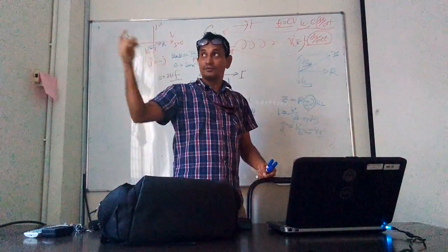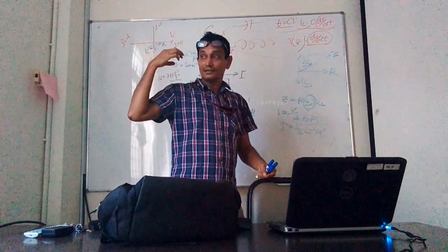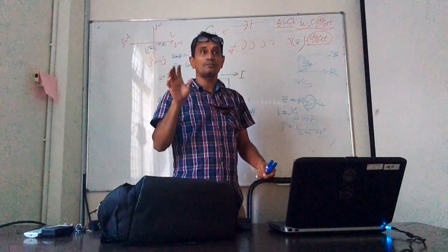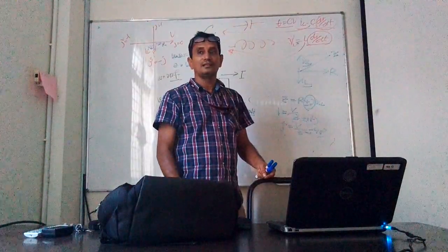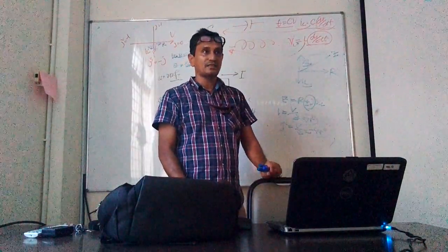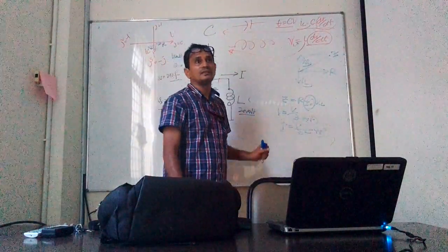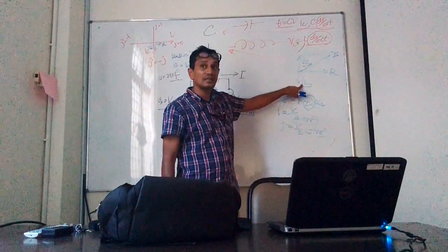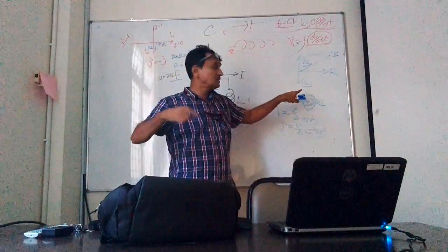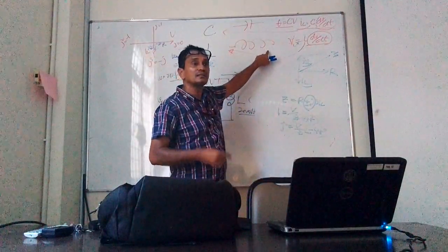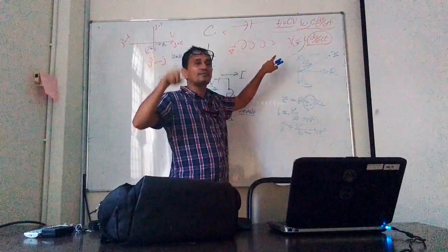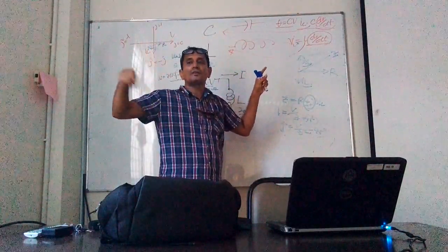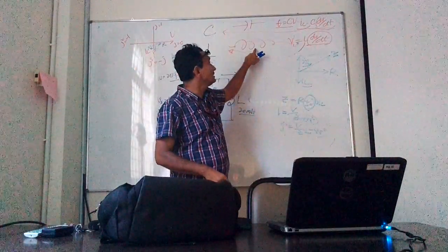If you force them to flow extra current, they will charge you extra. Your company, your industry will be charged extra. And that is called the power factor charge. They do it normally. That's why at the industry level, the inductive reactance is the most common, the motor, everything is inductance, yeah? You know, motor, generator, fan, everything, even your exhaust fan, has a lot of windings, yeah? That is actually this inductance.